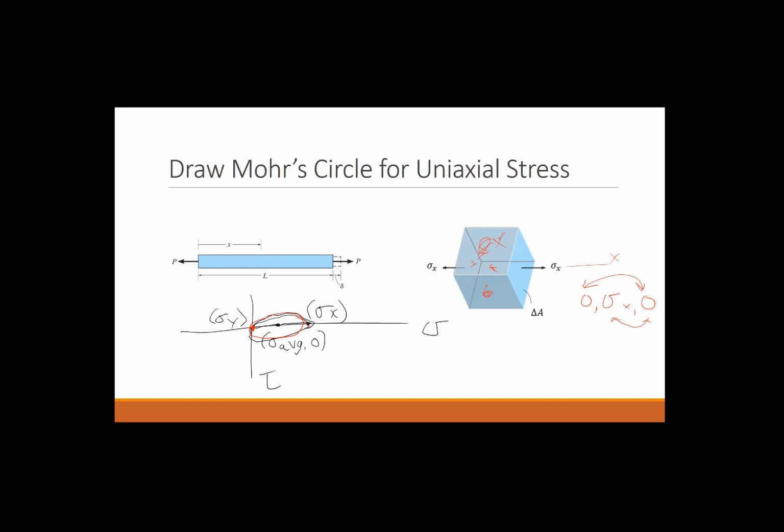So what does this mean in terms of our absolute maximum shear stress? Will it be in plane or out of plane? It will occur in plane, but it's a trick question. It will also occur out of plane because we have 2 identical circles. But we can figure it out just based on our in-plane values. It's going to be this maximum shear stress here.